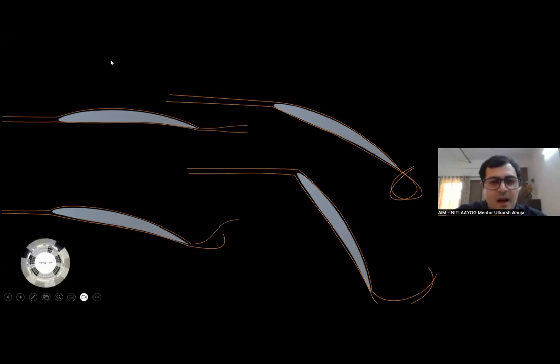That is true. However, that is not enough for this airfoil to create a lift such that the aircraft would be able to go airborne. In this situation, we pitch the nose of the aircraft upward such that the air speed going above this airfoil increases as compared to below.